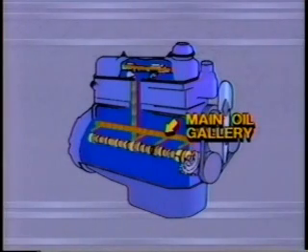Now, the final design you mentioned was the rocker arm shaft. Right. In this design, usually the rocker arm shaft is hollow and acts as the oil gallery. Here, oil is routed through a passageway off the main oil gallery to the rocker arm shaft. The rocker arm shaft then distributes the oil to the rocker arm bushings under pressure, and then to the other valve train components in the form of a spray or dripping oil.